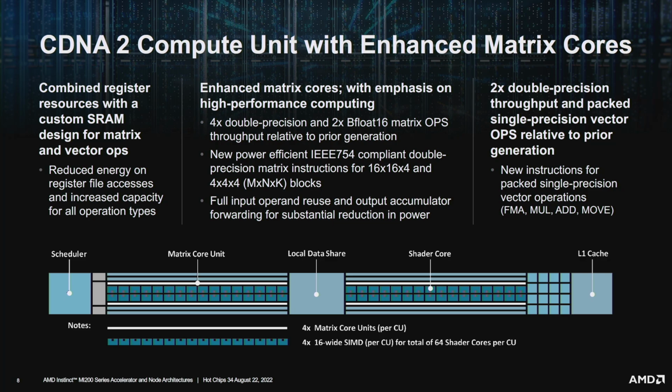However, we didn't stop there. These new data paths were utilized to add new packed single precision floating point instructions for commonly used operations to provide 2x throughput over standard FP32 ops. These capabilities are optimized for computationally dense FP32 kernels that cannot leverage the matrix cores. We've seen particular success using packed FP32 in n-body problems such as HACC, GROMACS, and LAMMPS. Finally, throughput of BrainFloat 16 was doubled to match the throughput of IEEE's 16-bit floating point, giving data scientists flexibility to use either format without compromise in performance.